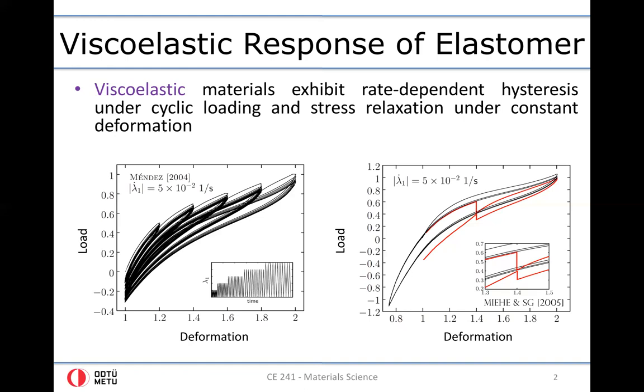Besides the relaxation test or cyclic test or the experiments conducted at different rates of deformation, one can also run experiments at constant rates of stress or constant stress values. These refer to the phenomenon of creep that we will discuss in the upcoming slides and chapters.